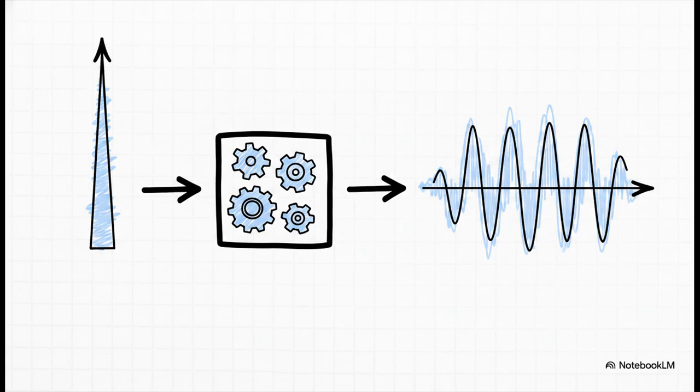So how do you actually find that impulse response? Well, you simply hit the system with a Dirac pulse. Remember earlier when we said convolving anything with a Dirac pulse just returns the original function? Because of that, if you feed an LTI system a perfect instantaneous Dirac spike as the input, the output you get is exactly the system's pure impulse response, h of t. It perfectly isolates the fundamental true nature of the system.